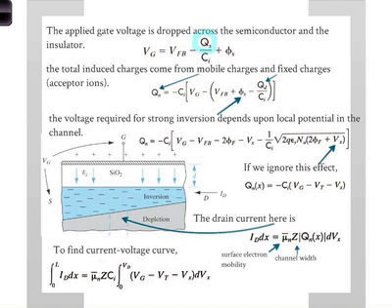We are ignoring any depletion in here because it's so highly doped. So the depletion region will essentially extend all the way to the end. We look like that, where this is depletion, this is inversion, without doing any calculation.